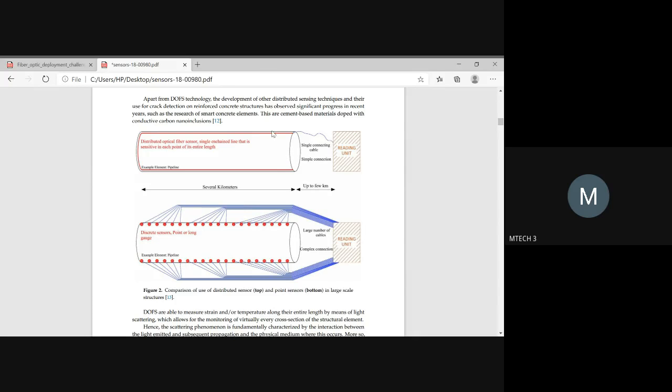That entire sensed data will be transmitted to the reading unit. The reading unit will receive the sensed data and transfer it to the controlling unit, where it converts the input data into readable machine language, right? Then that instruction will be passed on to the actuator and it works accordingly. And even if it is a very long distance, for several kilometers, this type of continuous distributed optical fiber sensor could be used successfully.